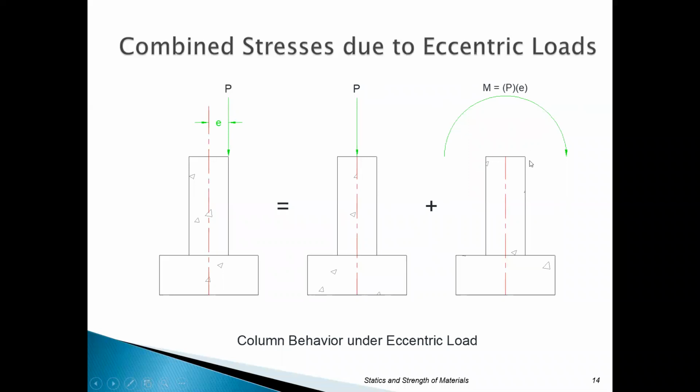It would be putting that in a compressive stress on that front side and a tensile stress on the back side. And if this was further located, not only just straight along the axis, but if it was like, say, one corner of that thing, then you could get a moment coming at you also. So this is what we call an eccentric load. Basically, you're using a process called superposition, where to calculate that, you calculate the normal stress, and then you calculate the bending stress, and you add them together. So that's what you're getting.